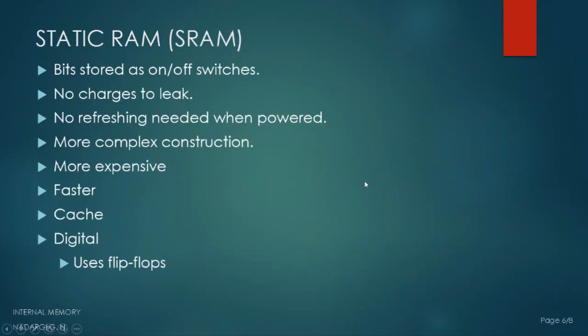Now let's move on to static RAM. Static RAM is a digital device. It is not analog like DRAM. The static RAM, that is SRAM, stores binary values using traditional flip-flop logic gate configurations. A static RAM holds its data as long as power is supplied to it.